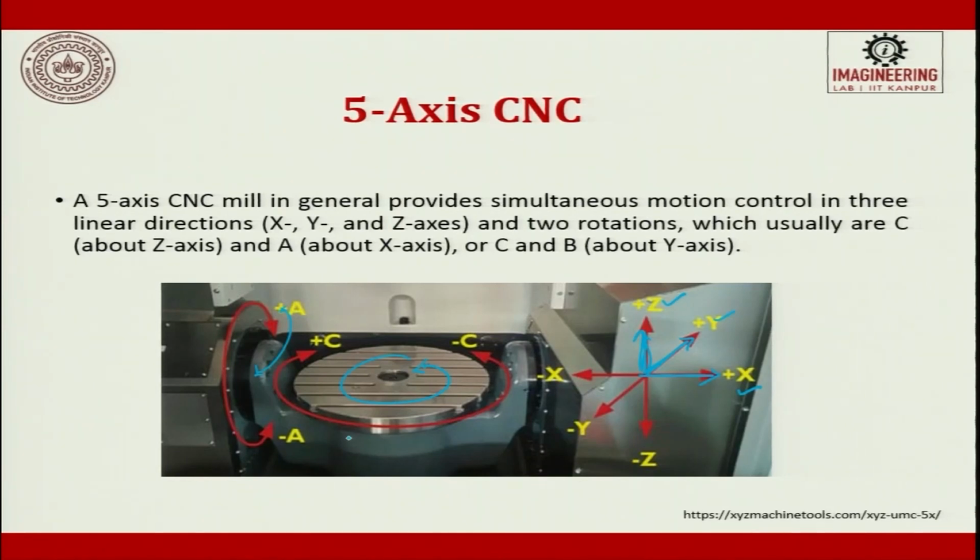So, for a 5-axis machine, manually writing a program is next to impossible, because as and when X, Y, Z keeps moving, you also will have 2 terminologies called R and theta. So, either you develop an equation, define the equation, and ask the program to go along with the equation. So, you interpolate the points, or you use CAM software. So, today it is advised to use CAM software for writing programs for 5-axis machines.